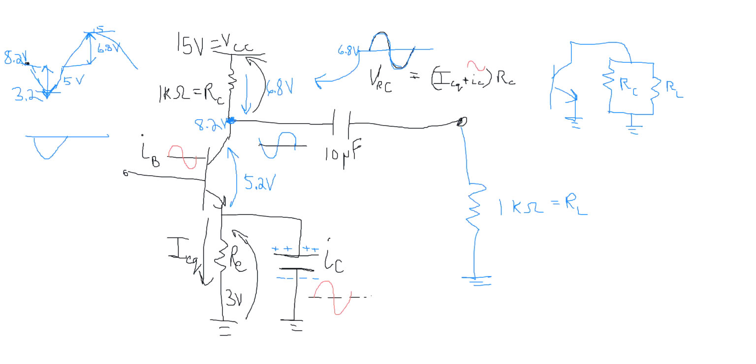That stopped all the current through the collector resistor. If we did that again now, if the transistor rose by 6.8 volts, we would have a total of 15 volts across the capacitor and the load. Now, the capacitor was sitting at 8.2 volts.